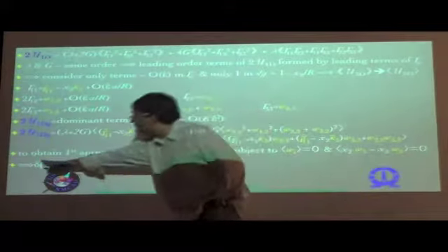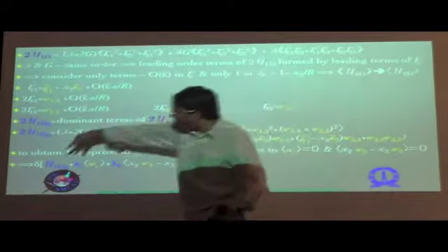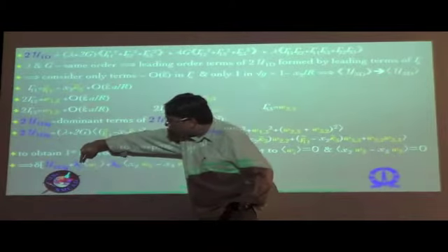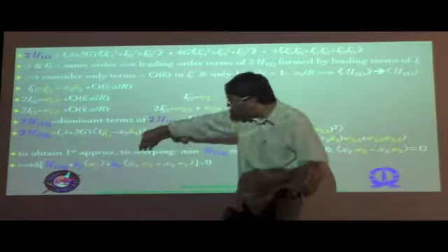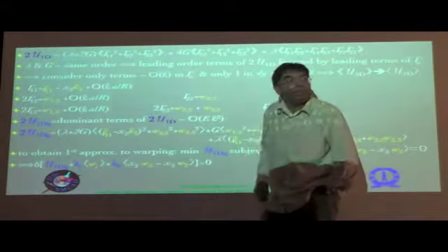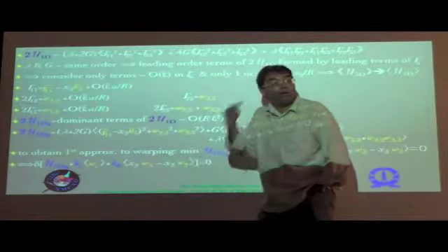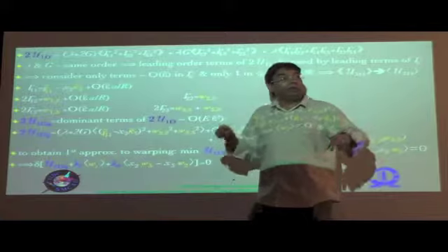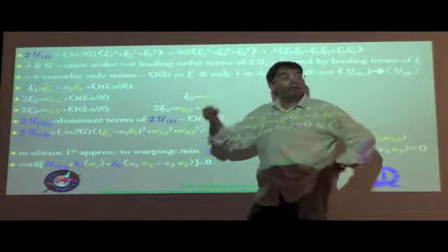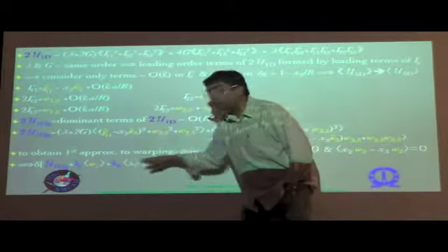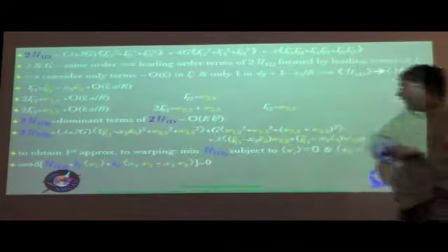So you have the first variation set equal to 0 of a particular quantity, which is not only U1D naught but also lambda 1, lambda 2, lambda 3, multiplying the integrals of w1, w2, w3, and then lambda 4 multiplying the integral of this. And these, remember, are actually just angular brackets. They are not the double angular brackets, even in a situation when you go to the higher orders of approximation or when you had those additional terms contributing. Because those are just integrations over the cross section that you have over here. That should be remembered as well.